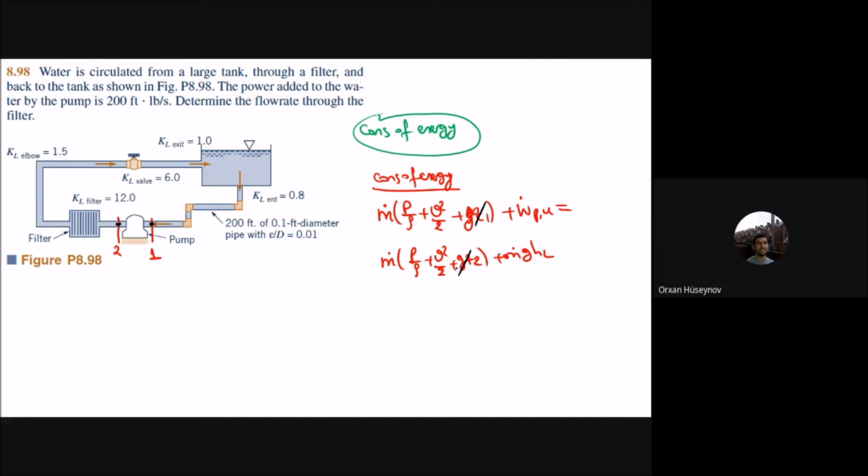And then you have that P1 and P2, there is a difference in pressure. Okay, the pressure is different between P1 and P2 because this one is the outlet of the pump and this one is the inlet of the pump. Therefore, you cannot erase these two terms here. And the velocity 1 and velocity 2. Since the diameter of the pipeline is constant, you will have that V1 is the same as V2. Okay. Now comes the work done by the pump, the useful part. This is also 0. Okay.